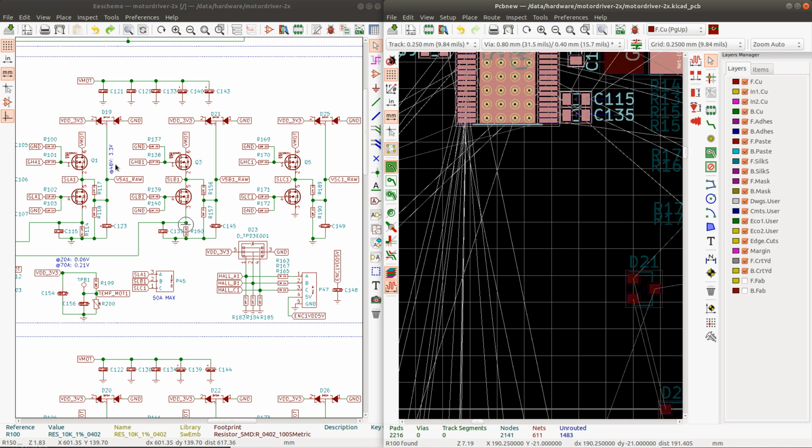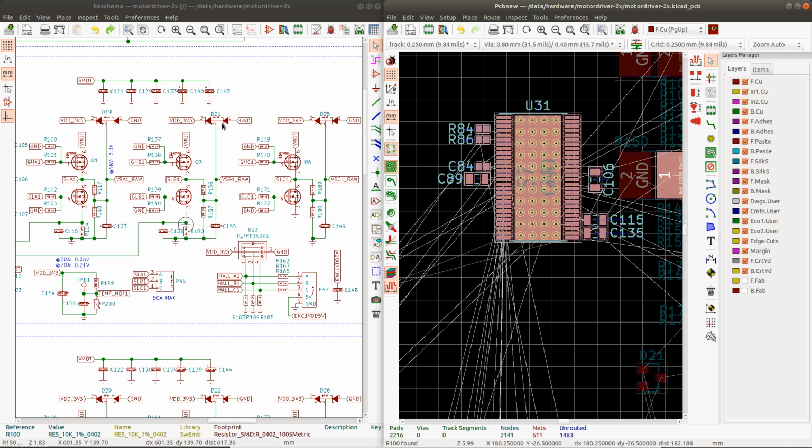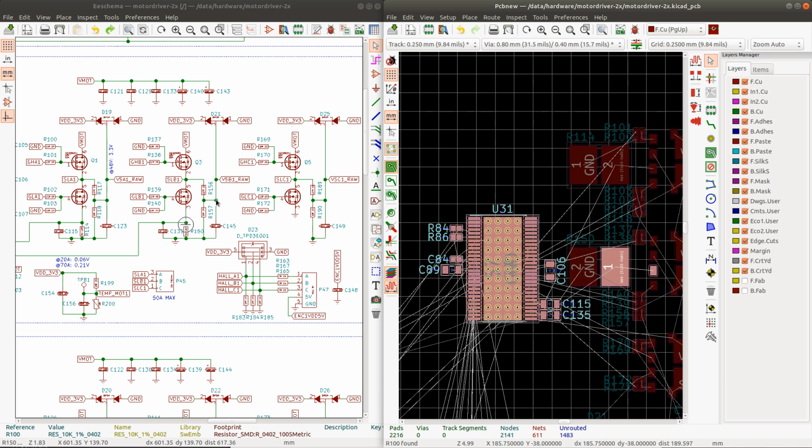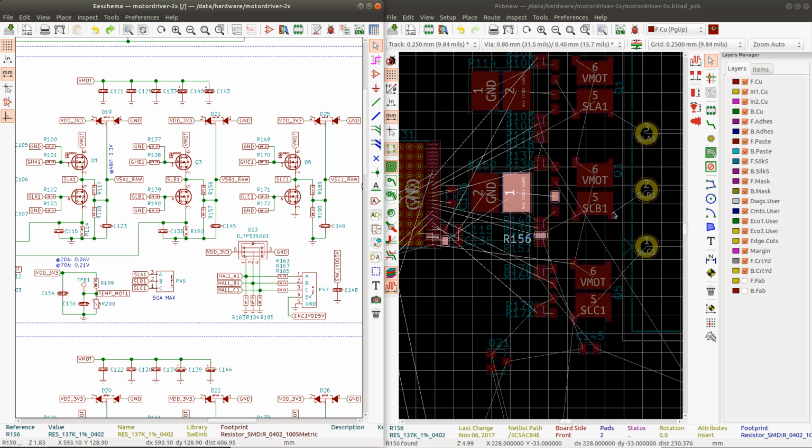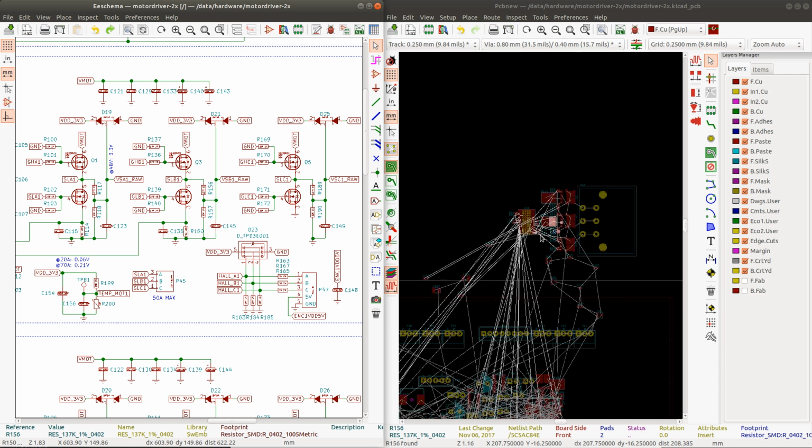I wonder if there's anything else that has to go here besides the diodes. So the diodes go to the voltage sensing resistors, which are here. I think that what I'll do actually is place this diode and this capacitor closer to the CPU. The capacitor will have to go there anyway, so might as well place the diode there as well.